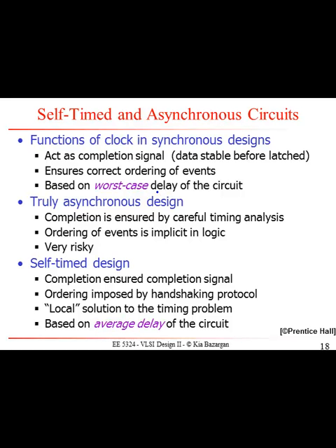All right, so now let's turn to the question of self-timing. Can we get rid of the clock signal altogether? And the answer is yes. There are things that you can do, of course with an overhead, to completely get rid of the clock signal and ensure explicitly in control logic that the operations are going to be performed in the right order.